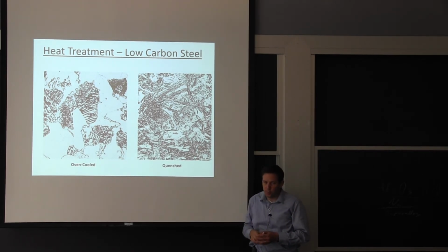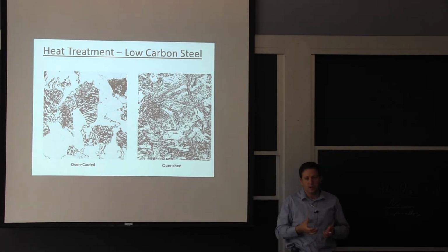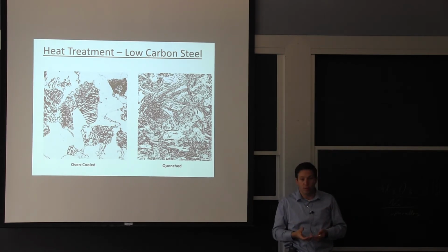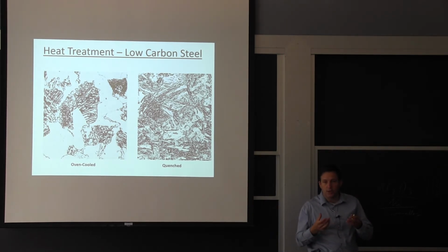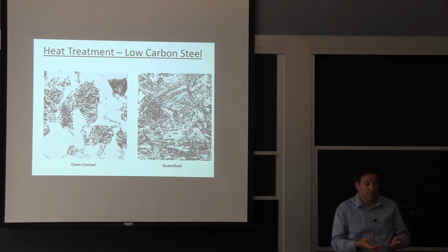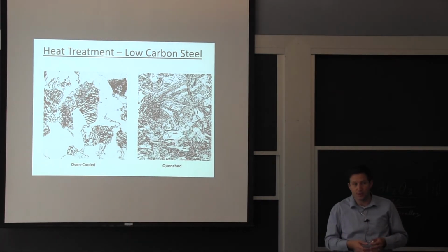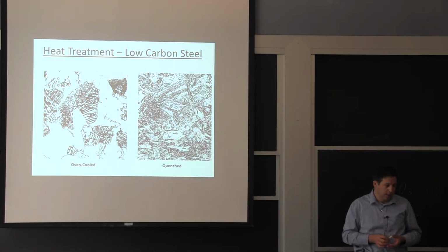If you remember our discussion with steel, we talked about quenching it. When you quench, you're preventing the diffusion and you're forming that martensite, and that's how you make it really, really hard. And again, you can temper that martensite, and that's how most people do it. A lot of times you want to soften it because otherwise you don't get any ductility whatsoever.